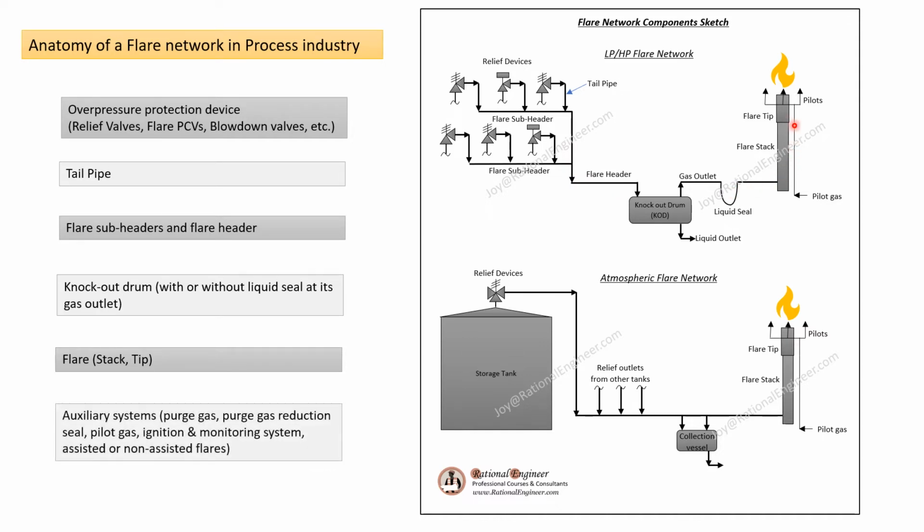Then there are auxiliary systems such as a purge gas to maintain positive pressure, a pilot gas to always keep the flare burning, ignition and monitoring systems, and so on.